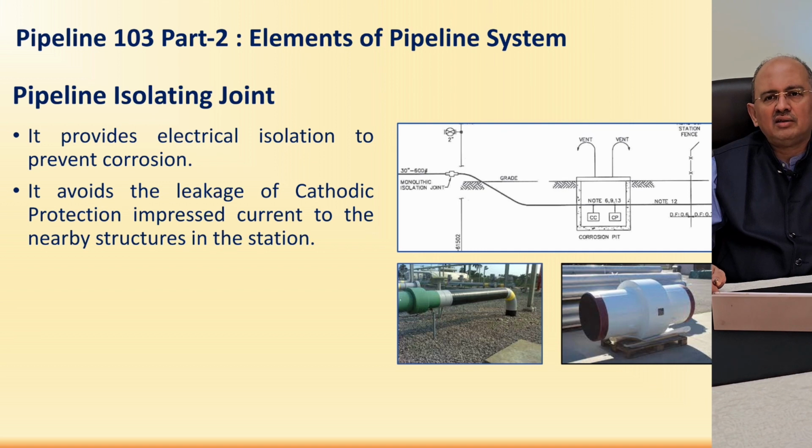So the main facility has all these pipe racks and structures and a lot of equipment which are grounded, and earthing is provided to all of them. So the impressed current that we are using to keep the pipeline passive from galvanic corrosion may leak through to the earthing system of the facility, to which the pipeline is connected. And if that happens, then the pipeline's CP protection may become very weak, and eventually a galvanic series can form, and then it can start corroding.